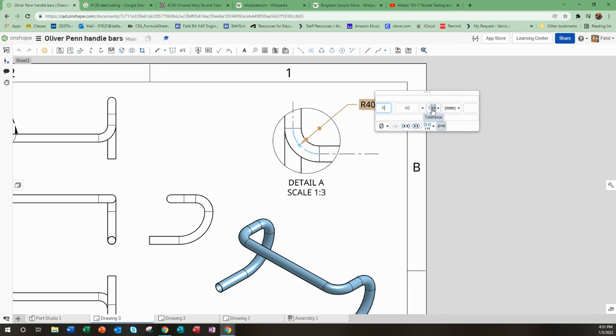And this is where I want to talk about the paperclip I had you guys bend. It's important to know that you will not always make a perfect part every time. What the engineer is doing here is saying, is it allowed to vary by plus or minus 1.5 millimeters? That's the case here, and that's pretty normal. I find that's a pretty good guess. This software made a pretty good guess at machine tolerances. That would be for a machine cutting this and making it, and you may be able to hold that type